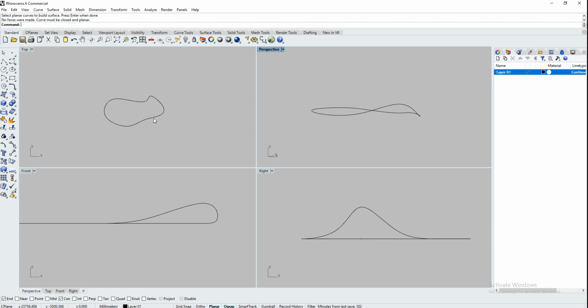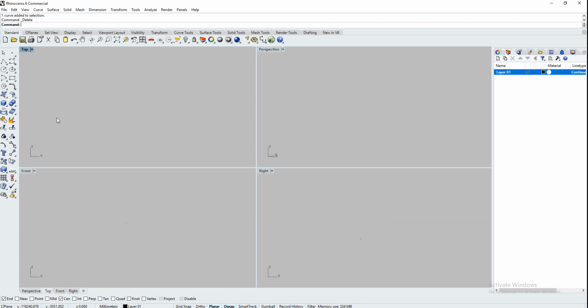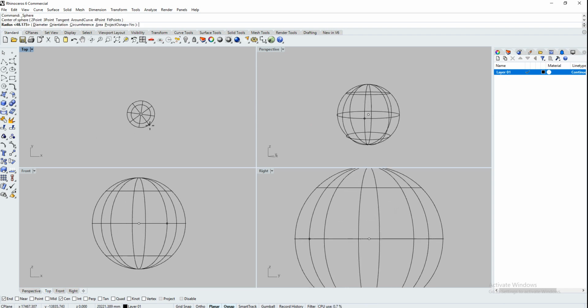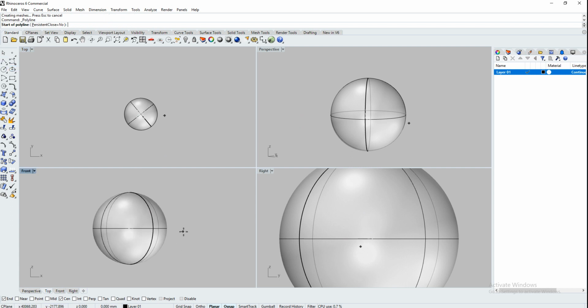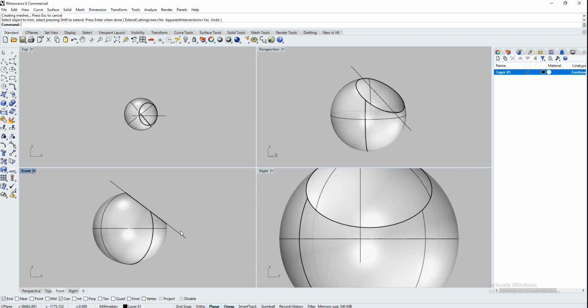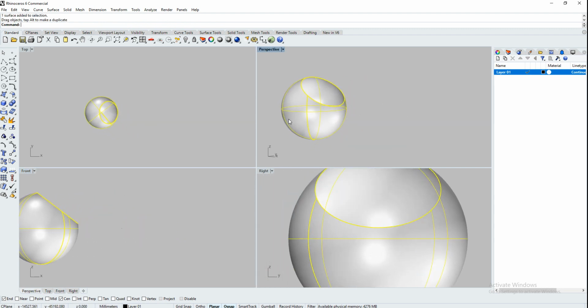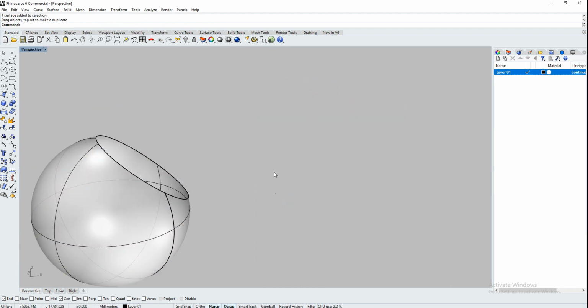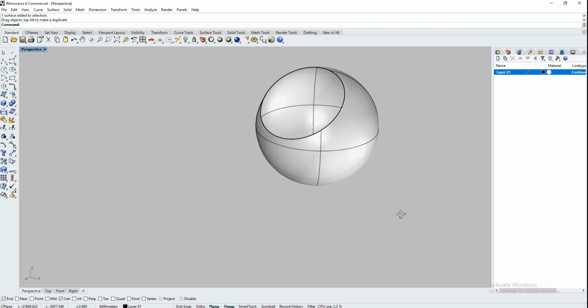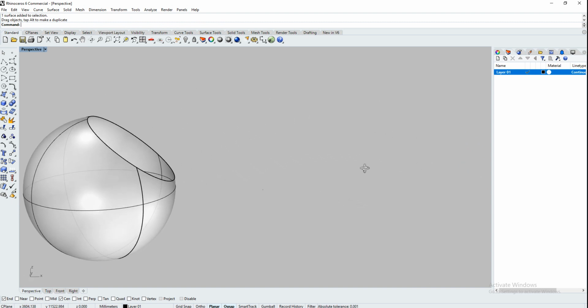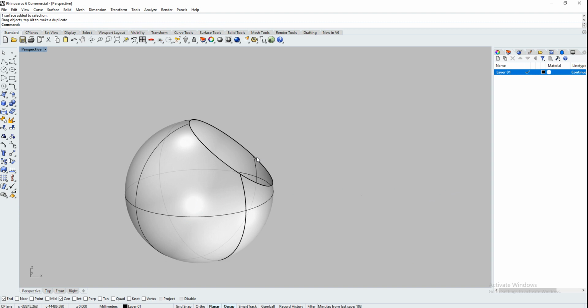but it's not the planar surface command. The planar surface command can also work with edges of a surface. So if I create a sphere here, then if I trim, I just trimmed a hole in this sphere, and this edge here, if that were to be a curve, it would be planar.